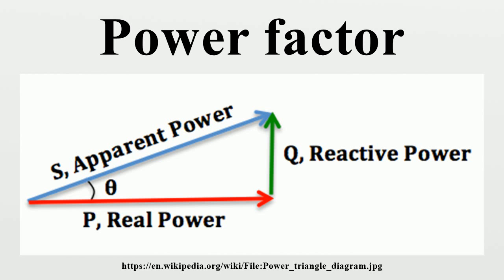The higher currents increase the energy lost in the distribution system, and require larger wires and other equipment. Because of the costs of larger equipment and wasted energy, electrical utilities will usually charge a higher cost to industrial or commercial customers where there is a low power factor.